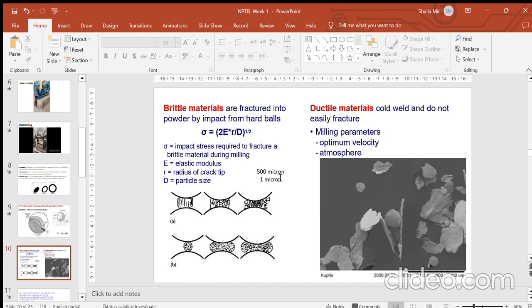Also this is very important to understand in our milling process, like how far we can go with milling. For example, if you are given a mill and asked to mill a substance to 1 mm, and you are able to do that, then you are asked to mill the same substance to 100 nanometer or 100 micrometer, you won't be able to reach that size, because prolonged milling does not have a significant influence on getting to a smaller size.